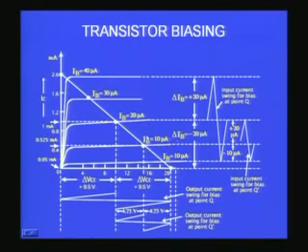Right. Now if instead of this point I had chosen my operating point at the beginning to be this point, then for the same variation of the signal at the input, you would find I will be moving from here to here, that is IB equal to 0 to IB equal to 20 microampere, and that way I will get into trouble, because if it goes beyond this, it is already in the cutoff region. I should never come into the cutoff region when I am designing an amplifier.